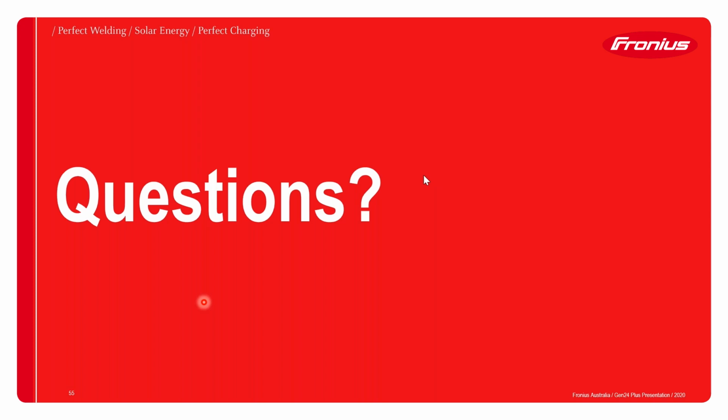Another good question from Gareth. We can oversize the PV to 150%. In the middle of the day, this DC energy will be lost if the battery is already charged. Consequently, we need to set the battery to charge only from clip energy, the wasted energy, or at least have the ability to charge only from 10 a.m. That's something that we are working on, Gareth, where you can tell when to charge and set different settings. But in general, you always want to oversize your system. And also remember, you have energy management where you can turn on and off different devices, or even store energy through hot water also. So that's also a solution there.